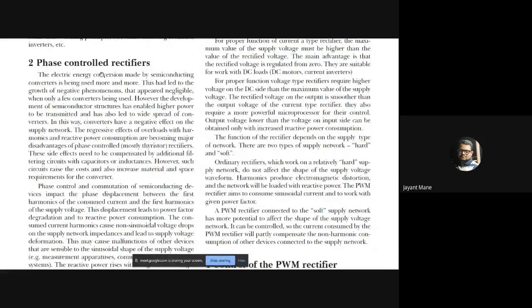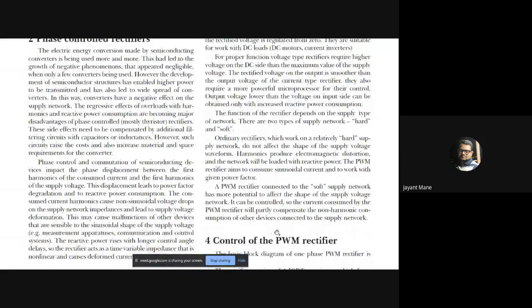Regarding the phase control rectifiers, meaning SCR rectifiers, they have given so much information that we already know, because we have studied these phase controlled rectifiers. So we know that we had to provide a gate pulse once in a half cycle, only once in a half cycle. Due to that, the SCR remains on for the further duration until the voltage goes to 0 or negative. At that point, the SCR gets commutated. So there is a natural commutation of SCR.